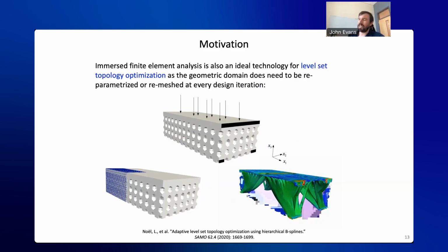And we actually take advantage of that fact in interpolation-based analysis. But the bright side there is if you're developing a body-fitted mesh for integration, the quality constraints that you need to have a good basis no longer apply, right? So you can actually develop pretty poor quality meshes and still be okay.